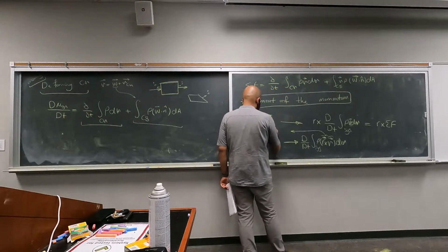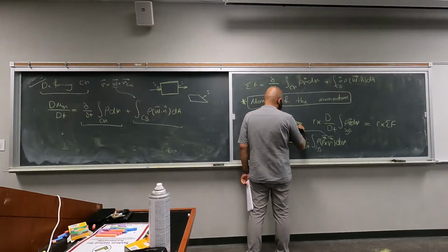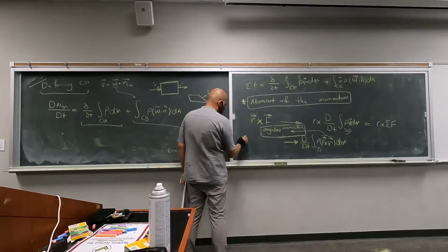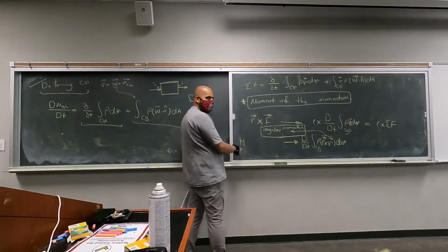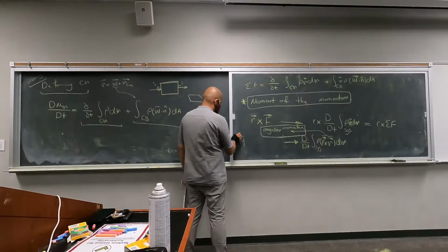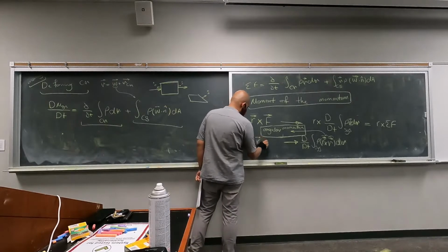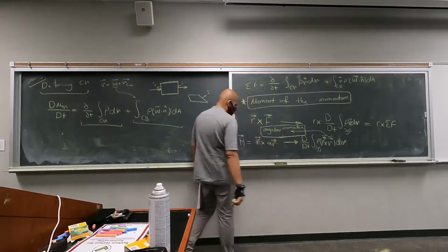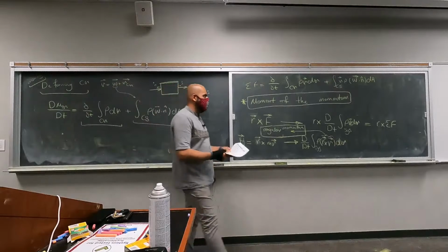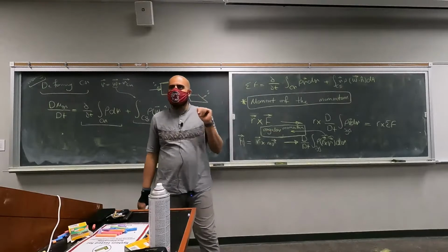So we have linear momentum, mv, and a specific angular momentum. And we usually use h for it. You haven't dealt with h in your dynamics? No? Okay. h is equal to R cross mv. It's called the angular momentum. So taking the moment of the momentum equation is going to give us the angular momentum equation, right?